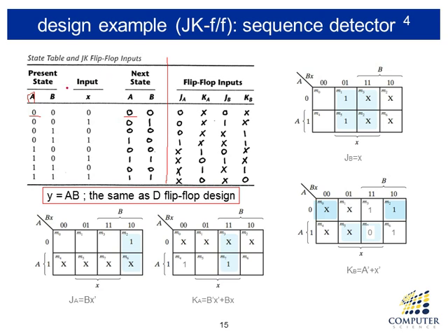But we are going to use a JK flip-flop. If flip-flop A is a JK, flip-flop B is also JK type. Then we know that a JK flip-flop has two inputs, and its behavior is such that if J and K are both zeros, the output remains unchanged. If JK is 1 and 0, the output becomes always 1. If JK is 0 and 1, the output becomes 0. If J and K are both 1, the output is complemented, or toggled.